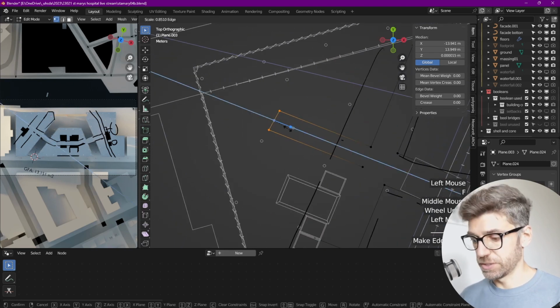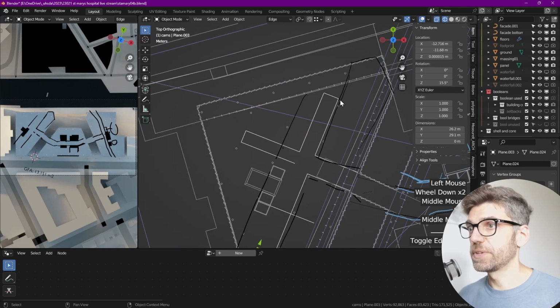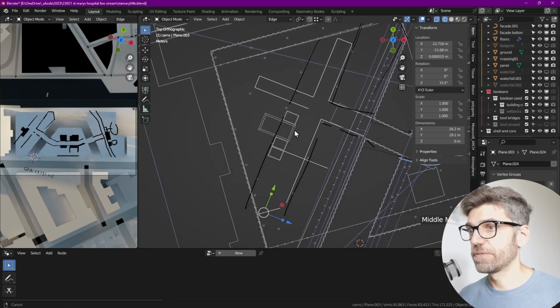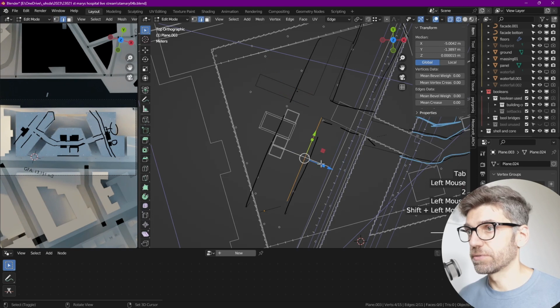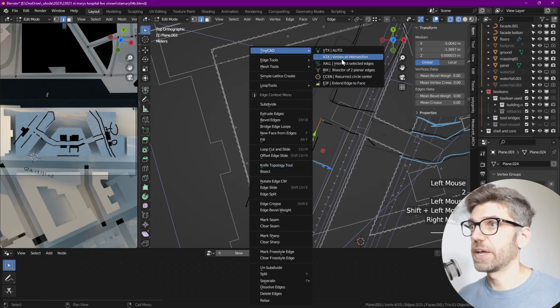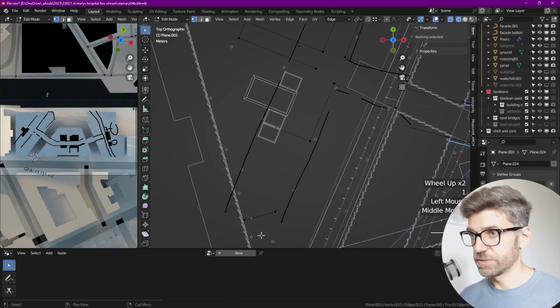Now let's make sure these are aligned. Now the only thing I'm worried about is from this distance to there, that should be okay. From there to there, that should be fairly okay. Great. And now let's intersect these two edges over here. So tiny CAD and intersect selection edges. And then let's get rid of these vertices over here.